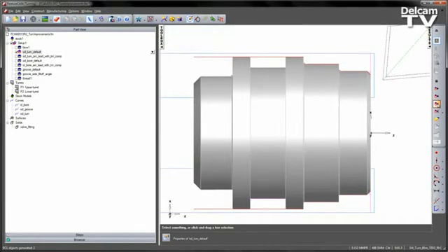Note the tool approaches from the same location, only this time we get the arc move. I get the profile as I would expect, and then we arc off. This nice smooth transition allows us to machine longer parts in different segments. We then have a nice smooth transition into each segment to try and reduce any witness marks that might occur on the part when finishing. It's worth noting the position of this. You can see we start immediately on the arc.